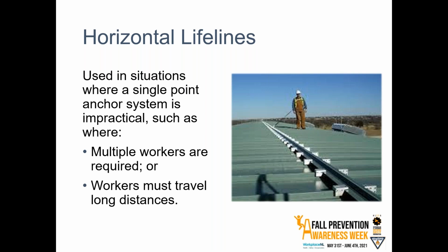But these can be used for one worker or for multiple workers. And usually they're employed when a worker has to travel a long distance in one direction. So often there is that track or rail that they're attached to. So in the picture I've got here, I've got an individual who's up on a rail car. So this is a train scenario. Obviously, he's over his limit for working at height, but the particular system he's got in place here allows him to walk the length of that rail car, and let's just say he's opening vents or something like that, without actually getting, again, near to the edge where he may fall.